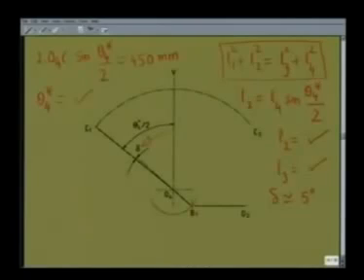So, we have modified the design to satisfy three requirements, namely the field of wiping has to be symmetrical about the vertical line O4V, has to be of a particular width, and also there should not be any quick return effect such that the wiper blade takes equal time in the forward motion and return motion. It should not go very fast in one direction and very slowly in the other direction, which will definitely disturb the driver.